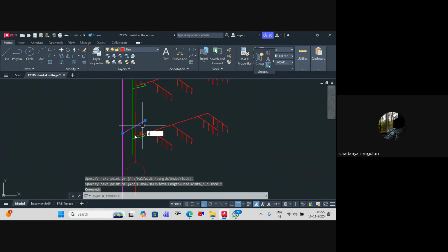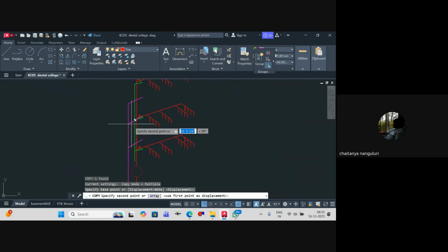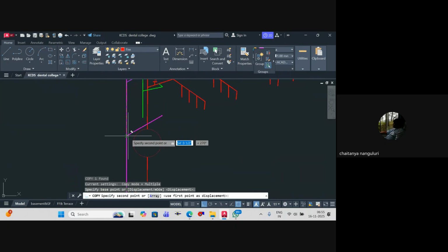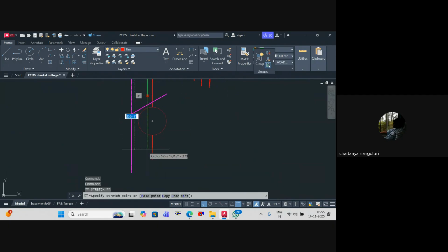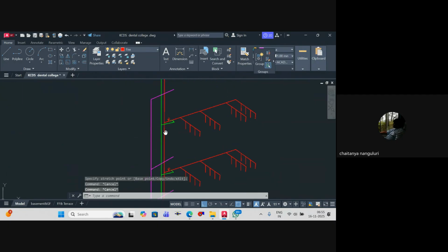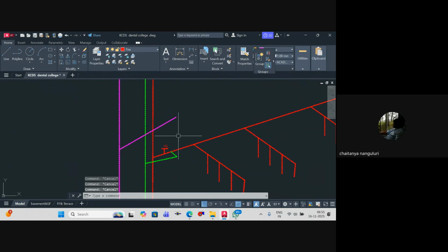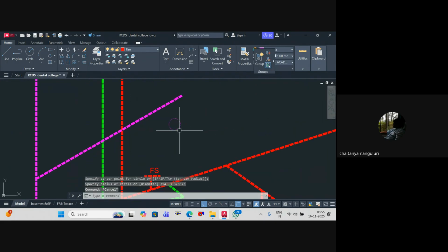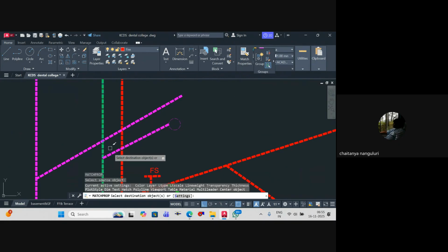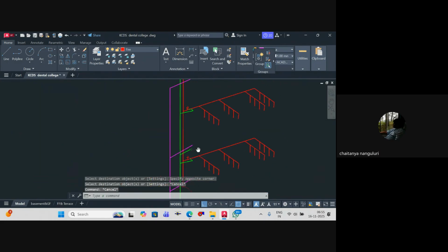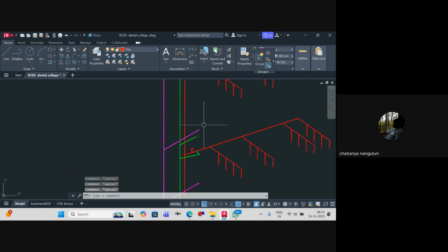Similarly, you have your hydrant valve. In all the three floors, you'll have your hydrant valve. So when you have a hydrant valve, automatically what will happen? Near the hydrant, you will provide a small flow drain provision. From the flow drain also, you'll connect it to the floor level, near the floor level, beneath the yard hydrant location. So that drain and this drain also you can combine. There's nothing wrong with that.